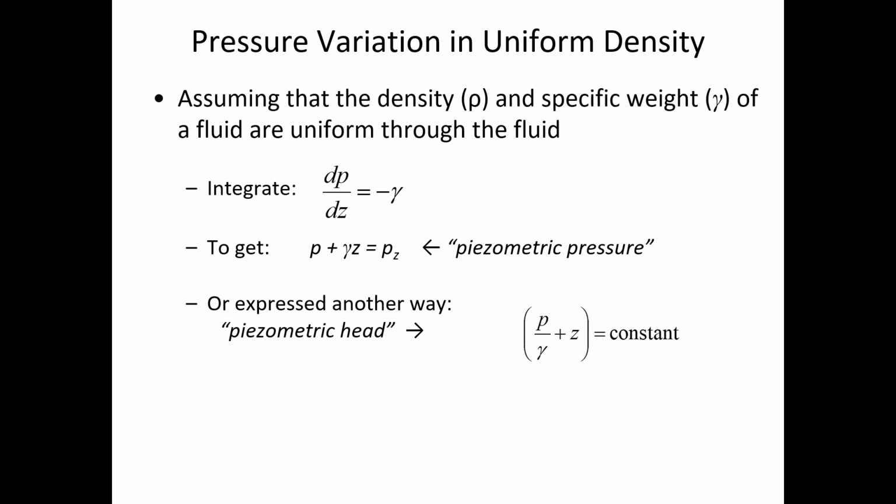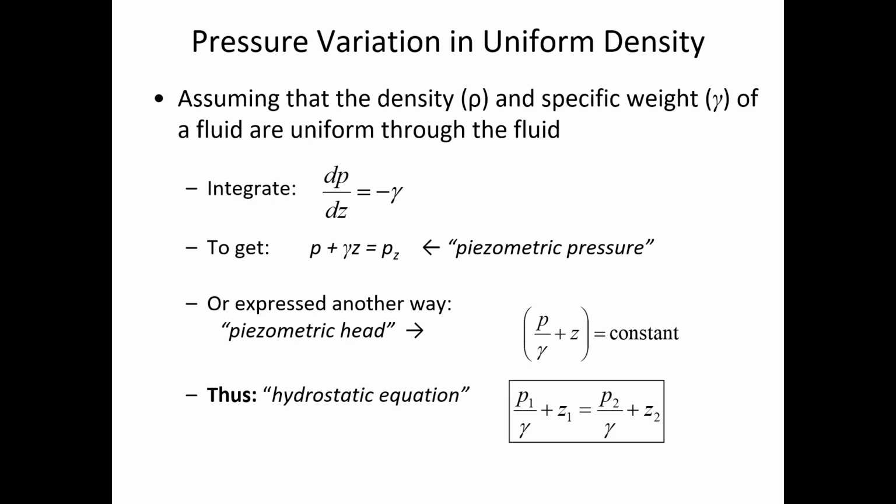Just as you go down through the fluid, the pressure goes up. So you're losing elevation, but you're gaining pressure. There's just this exchange between elevation and pressure that occurs in a static fluid. So that's the hydrostatic equation. I've just written it out on the board, and we see it on the screen here. We can use this formula to find out what the pressure is at a certain depth.